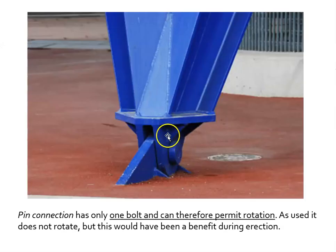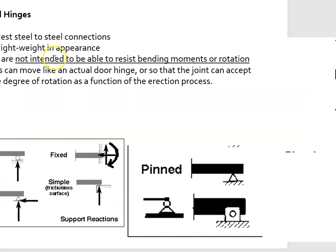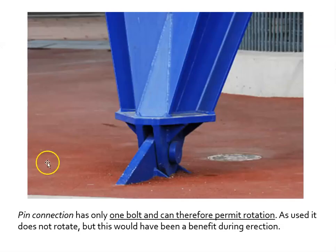All right, so its connection, everything is happening right there. So the enormous weight from above, and I just gather that it's enormous based on the size of this column, is coming down. It's going through this plate into these two plates, and then all that energy is transferred right through that bolt into this base plate that's grounded in the earth there, or in the concrete base. So you have to think about that snow load coming down, transferring through the bolt into there. Okay, so that's that. It's not able to resist rotation, really. Not designed for that.